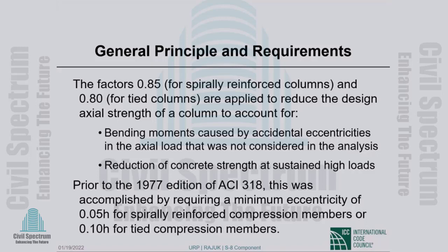I think I did mention on the first day when we were talking about material aspects that the strength of a material or a structural member made of a material increases the higher the rate of loading. Okay, if the load is applied at a high rate, high speed, then you will measure higher strength than if the load is slowly applied.